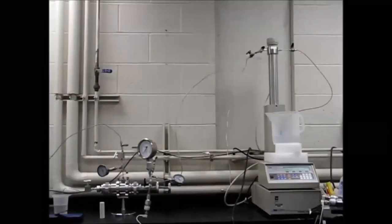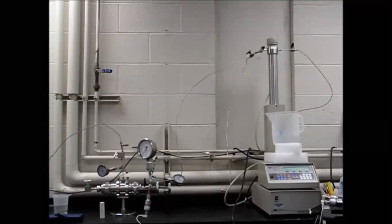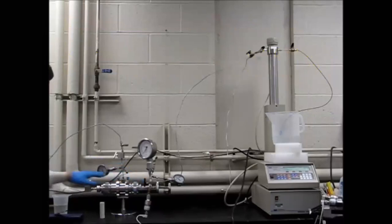Procedure of this experiment is basically, first we measure the dimensions of the core sample, L and the radius R, using the caliper and ruler. Number 2, open the pressure acquisition software and then calibrate the pressure sensors. Number 3, make sure all fittings are tightly connected, otherwise you might have a leak, and that will lead to inaccurate measurement. Number 4, start the pump with the lowest flow rate, which is 1 milliliter per minute, then monitor and record the pressure when it's stabilized, the pressure at the beginning and the pressure at the end of our core holder.